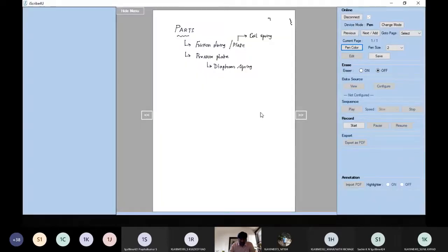So once again I come back. When I am talking about the design of clutch, it means we are trying to find the friction plate. This is what exactly we are going to design. So when I say friction plate, what are the different dimensions you are going to find? You will be finding D1, the internal diameter, D2 and H. H is the thickness. You will be finding this thickness. So D1, D2 and H we will be finding. Now other dimensions will follow.